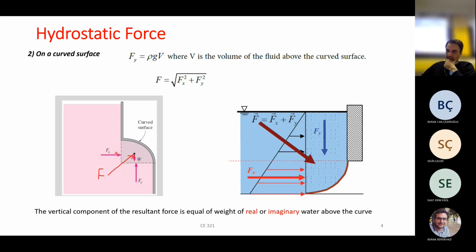For Fx, the problem is easy. I have two ends of this curve, and this line is the projection of the curve on the y-axis. Therefore, assume the problem changed to a simpler one, calculating the resultant force on a vertical surface. You know how to calculate this Fx. So let's check how we can find Fy, the vertical force acting on this curve.